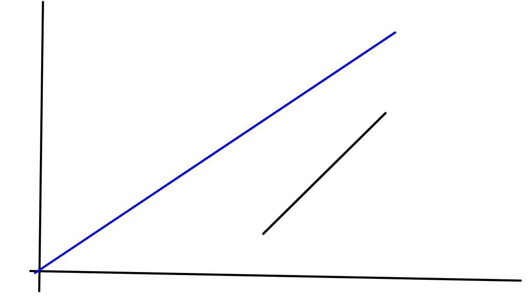Now what you have to do is mark which point is the top point and which point of the operating line is the bottom point. Remember that we have defined our top as 2 and the bottom as 1. As you can see, in this operation our gas is coming from the bottom from point 1, and it has lowest composition.